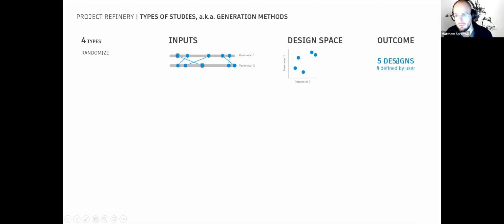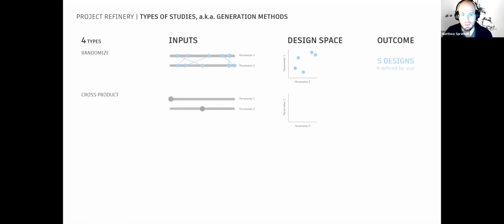You tell Refinery to stop after, in this case, 5 options, but you could say 5,000 options. It doesn't get you to high performing options automatically, but it will show you where they sit in your design space, and how they perform. It just won't curate them or evolve them to higher performing.